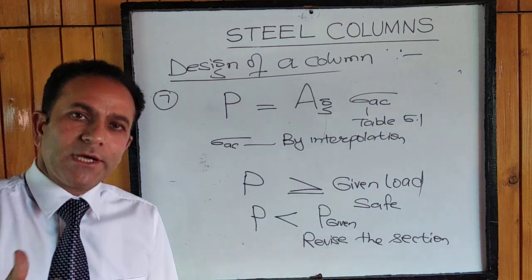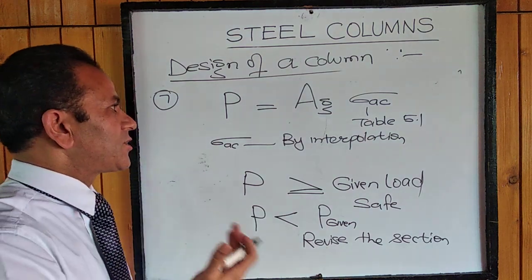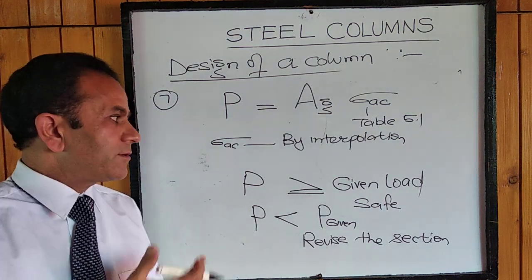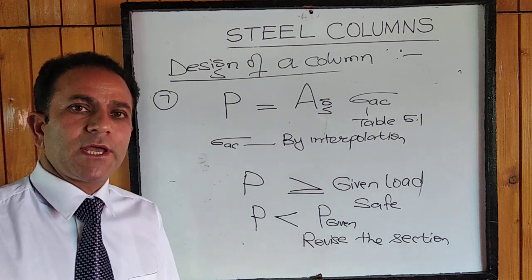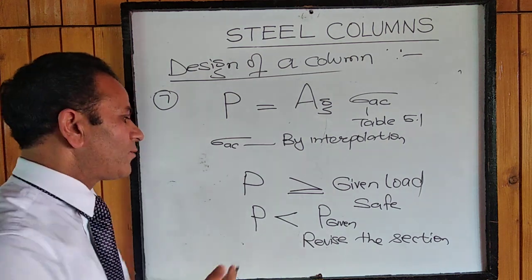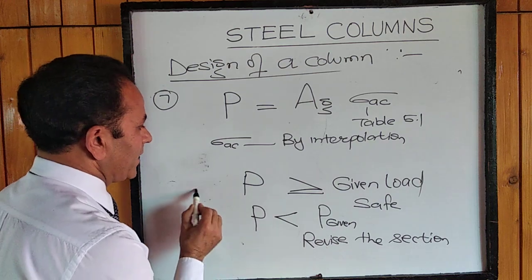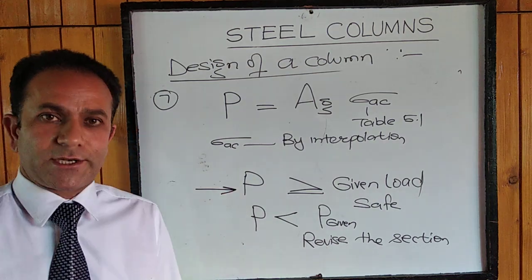We'll have to take a bigger section, a heavier section, a section which will have more area and hence give us more load carrying capacity, and revise the steps to find out another section. Ultimately, this condition has to be satisfied.